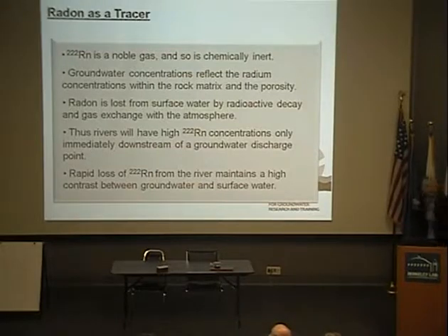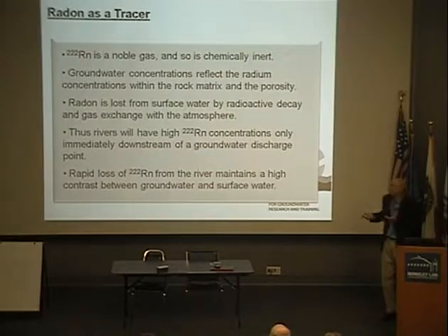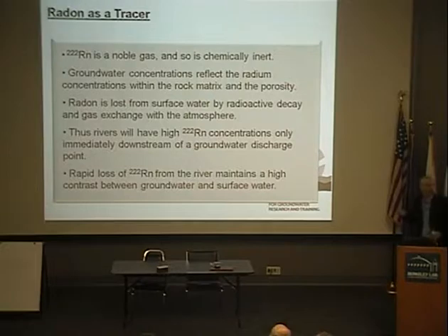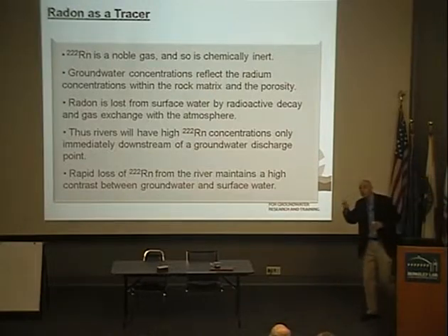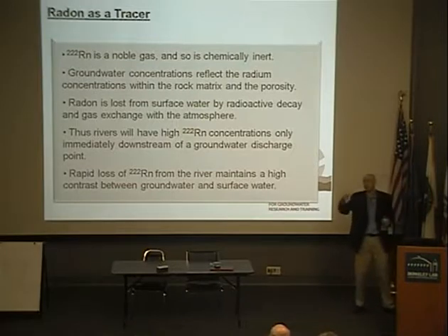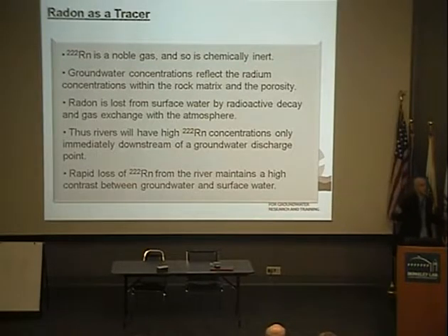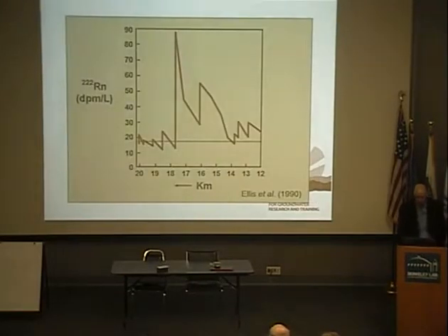Because it's continually lost, that actually maintains the high contrast between groundwater and surface water. So the fact that it's lost is actually a plus. Whereas if you're measuring a solute, if there's a lot of groundwater discharging to the stream, if you're measuring a solute like chloride, eventually that stream will have the same chloride concentration as the groundwater. So it won't be useful anymore further downstream. That doesn't happen with radon because it's continually being lost. So it maintains that high contrast.